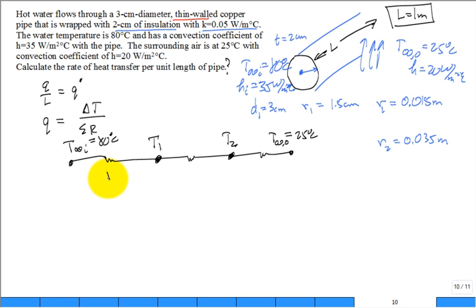So this is going to be 1 over h1 A1, the inside, and 1 over h2 A2, the area outside, right? And what's the resistance to conduction through the insulation? It had a natural log of R2 divided by R1, divided by... I know that you have the equation sheet available, but is that the right equation? You're helping me over here. Is that good? Very good. Now somebody says I'd like to replace that A1.